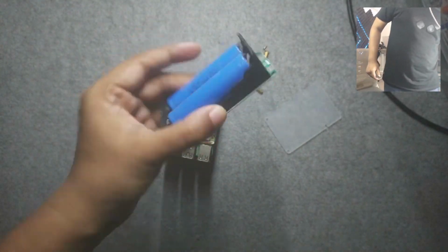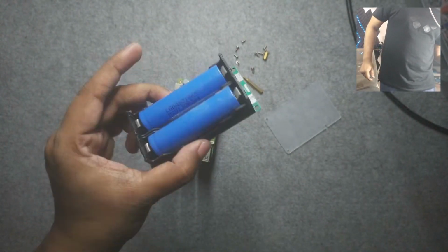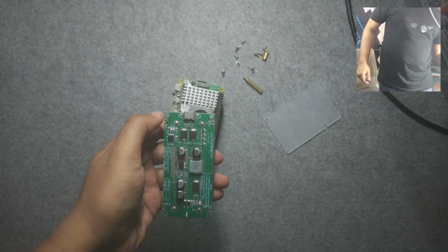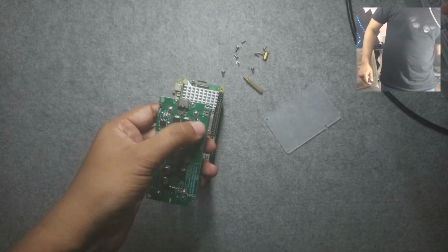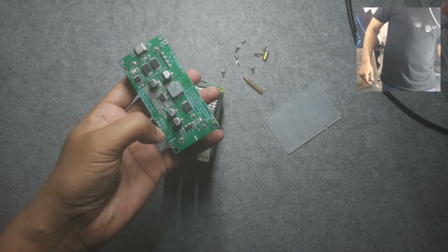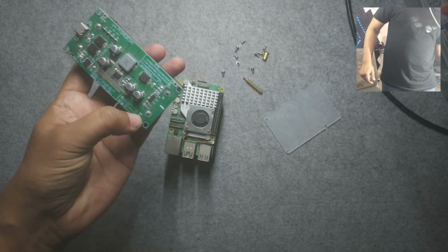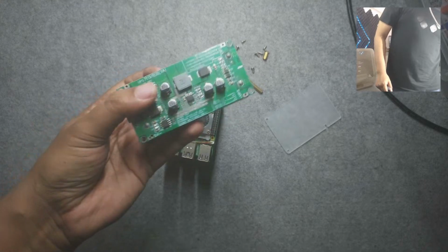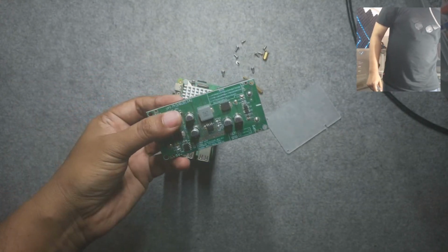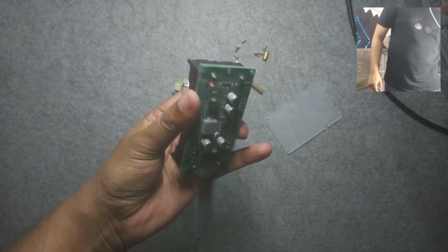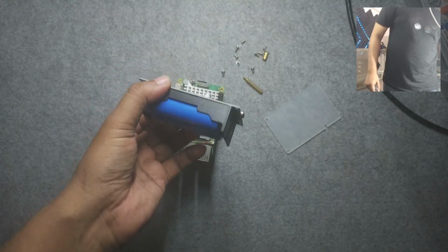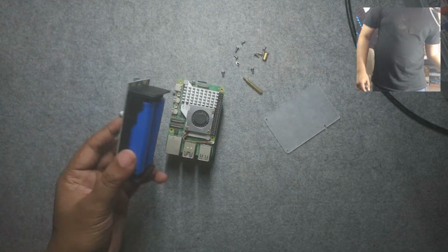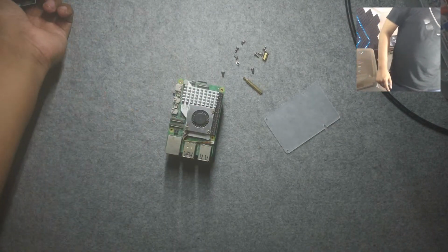also a 2S setup, which actually does boost and provides 12 volt. It takes USB power, or you can provide normal 5 volt power in as well, and it will give you regulated 12 volt output, which operates in the boost topology. And I'm trying this one out for the UPSs that I'm working with. Sorry, the router UPS that I'm working on.